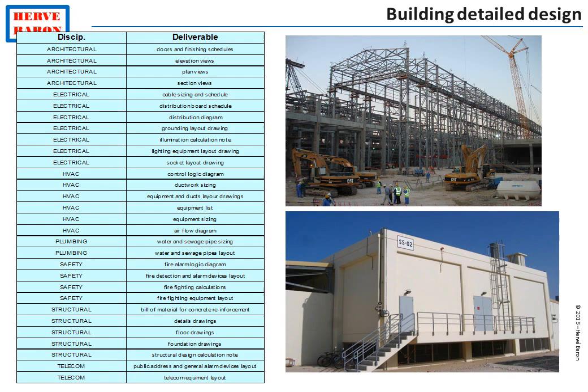The building construction contractor will prepare all the detailed drawings and all the bill of quantities in all disciplines, including structural, electrical, HVAC, plumbing, and so on. These drawings will be reviewed by the civil engineer of the EPC contractor, who will mark up its comments. Typically, these comments will include the provision of openings in the floor and the walls for cable entries into buildings.